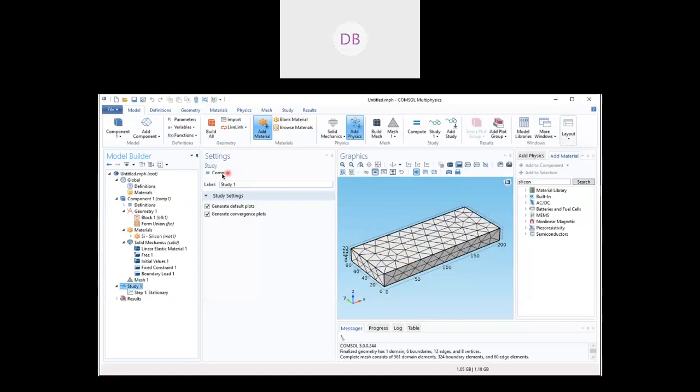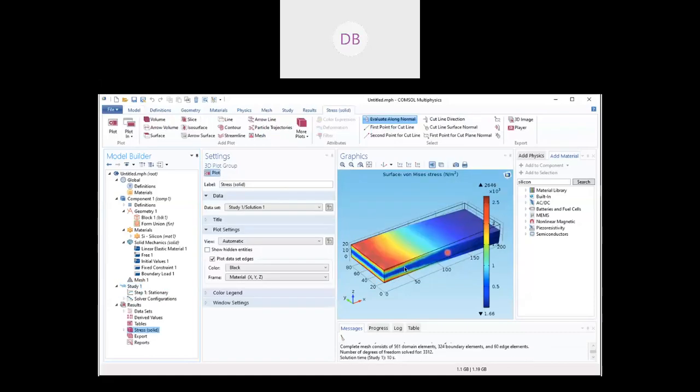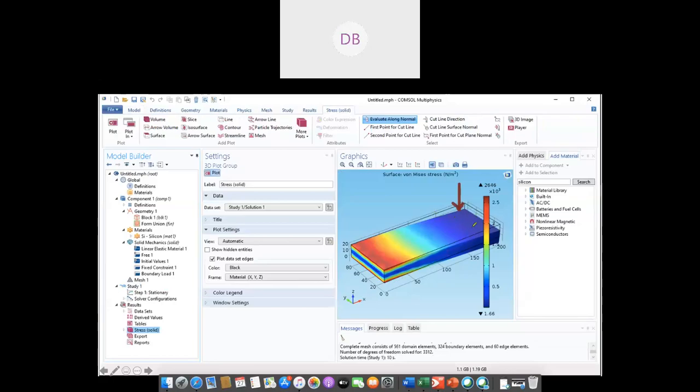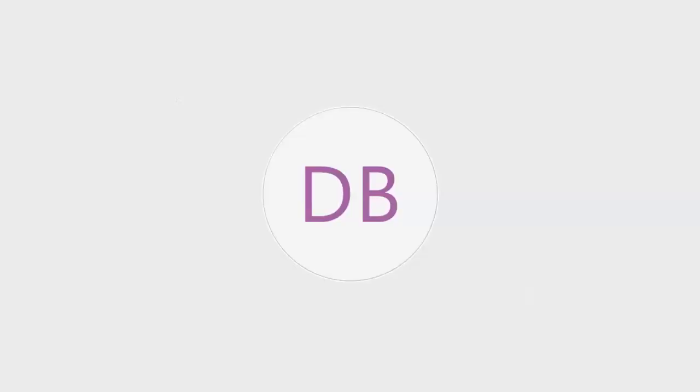When the force is applied in this direction, it tries to move downwards. So here, this bending is directly proportional to the amount of force that is applied. So obviously, if some microorganism or some virus element is falling onto this, there's a deflection that is happening, and this deflection is directly proportional to the mass that is deposited on this.